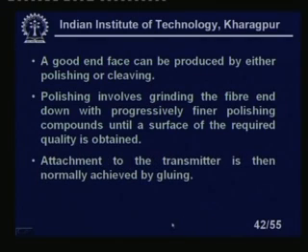This light source, as I told you, has a spherical lens, so the light which is coming out from the source falls on the spherical lens, and when it goes out of the lens, it is all parallel lines of light. So that will be launched into the fiber optic cable. Attachment to the transmitter is then normally achieved by gluing.